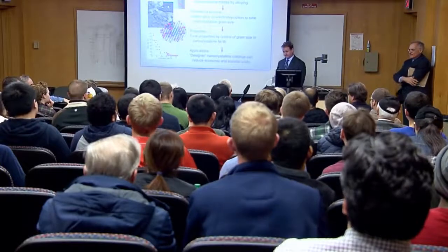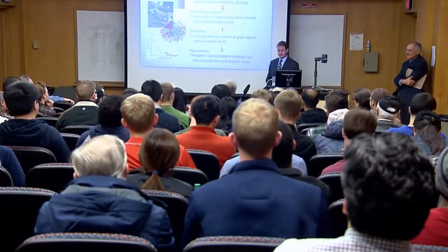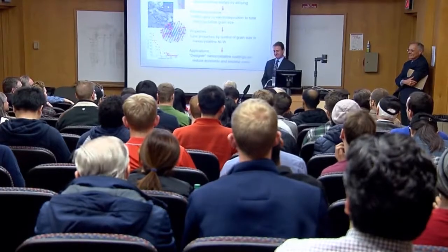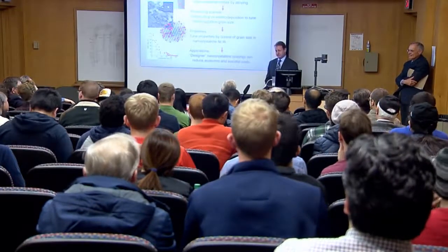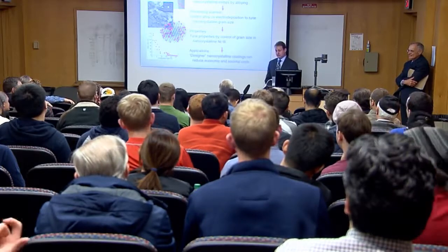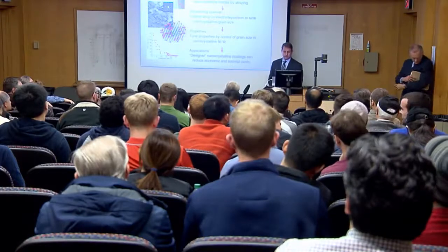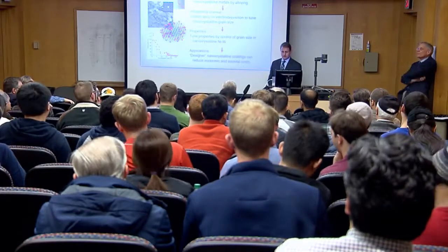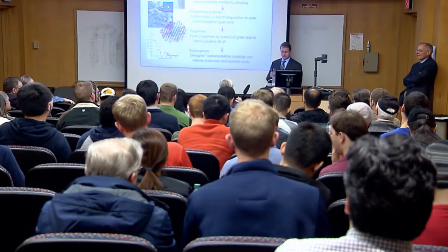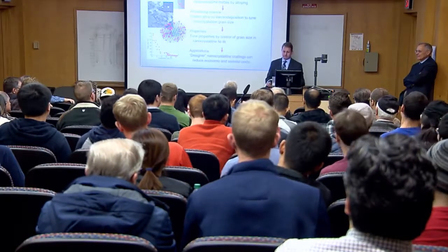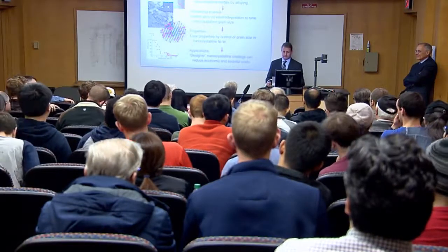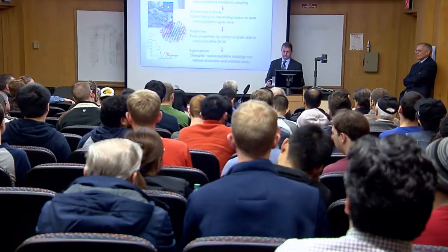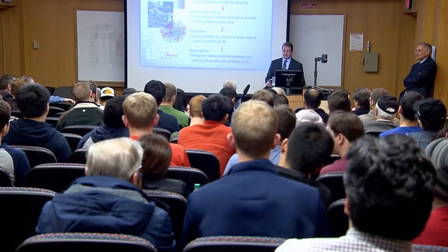I'm sure there'll be lots of questions. Professor Ernst, I know it's all my fault because of the way I advise you to give these presentations, but I think you gave us a very simple picture of what the tungsten does. You said it lowers the grain boundary energy. Is this really true? I'm thinking if you just had the grain boundary and you bring in tungsten from outside, would the grain boundary energy really go down? Or is it such that having the tungsten in the grain boundary is energetically more favorable than having it built in the grain crystal structure? And then also, the tungsten could in principle actually change the nature of the grain boundaries, and it could impact the texture of the material that forms. And that could also reflect back on its mechanical properties. Do you have any knowledge about these questions?